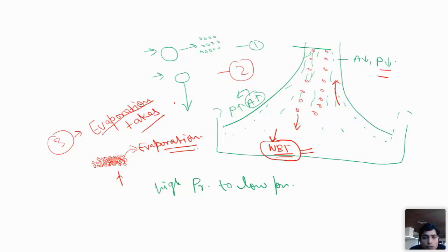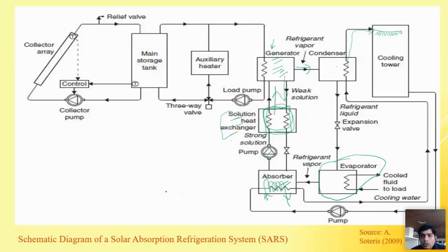So I'm again reminding you, there are three basic reasons by which we are able to decrease the temperature of water molecules. First, conversion of a bigger drop into smaller ones. Second, contacting with the hot air going in the upward direction. And third is the evaporation. By these three methods we are able to convert this high temperature water into low temperature water.